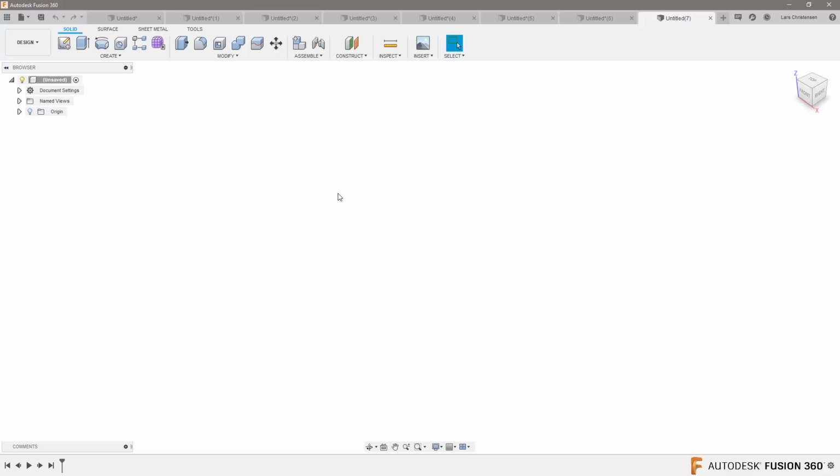So, to figure out slides in a mold, and this is how I would do it, you would never worry about the movement per se, because what you're concentrating on is the mold closing, and then everything else will come from that.